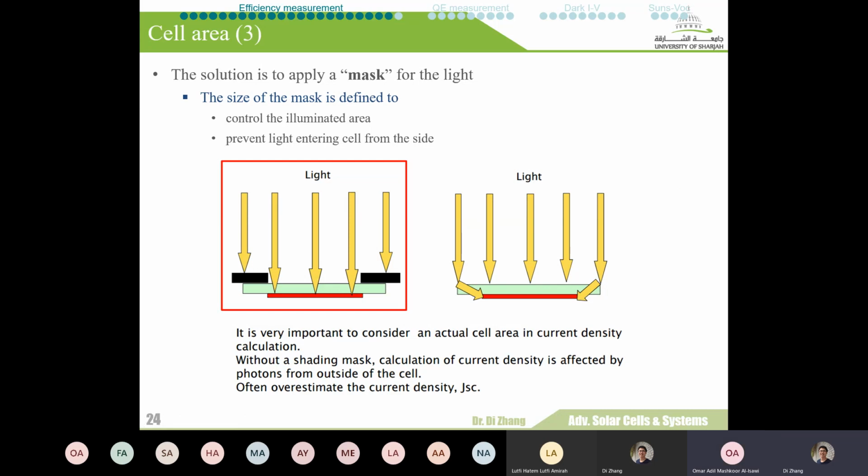Questions? Yes. The red one is the solar cell, and what is the blue one in the figure? The red one is the solar cell, and typically when you produce especially thin solar cells, they are very thin, so by themselves they cannot exist independently. So typically, what you do is produce the solar cell on a piece of substrate. For silicon, it is not a thin solar cell, and the wafer is very thick. So for silicon solar cells, we can just use the wafer, and all you see in silicon is just the wafer, and then we do different modifications on it.